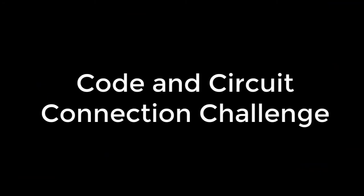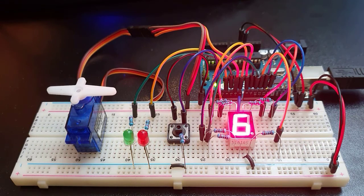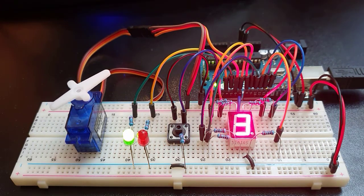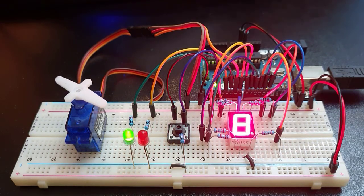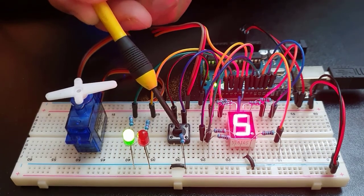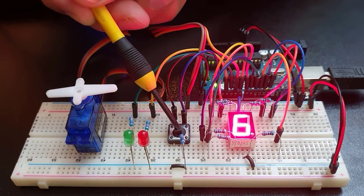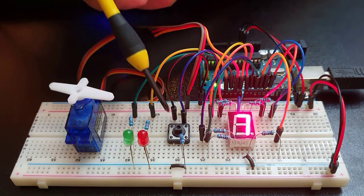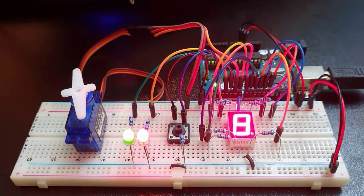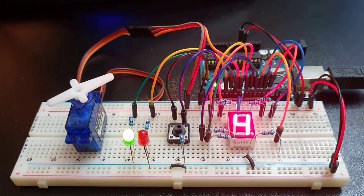And now, for your code and circuit connection challenge, I challenge you to create a similar prototype consisting of a 7-segment display, a switch, a servo motor, and an additional 2 LEDs, green and red. The digit counter counts down from digit 9 to digit 0, while the servo motor rotates synchronously from 0 to 180 degrees. As the digit counter counts down and the servo rotates, the green LED blinks at 500 millisecond interval. When the operation resets, either by pressing the switch or reaching the count to 0, the red LED turns on, and repeat the process again.